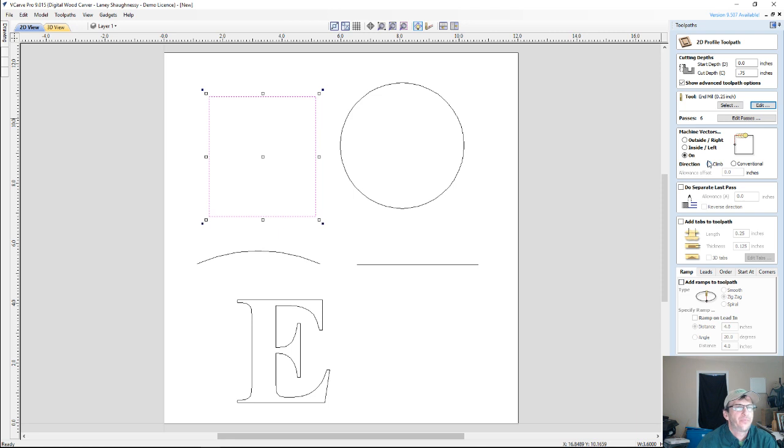One example: imagine I was doing a series of lines surfacing a wasteboard, where my cutter comes across the grain, then raises up, comes back to the starting point, and cuts again, instead of that back and forth motion.